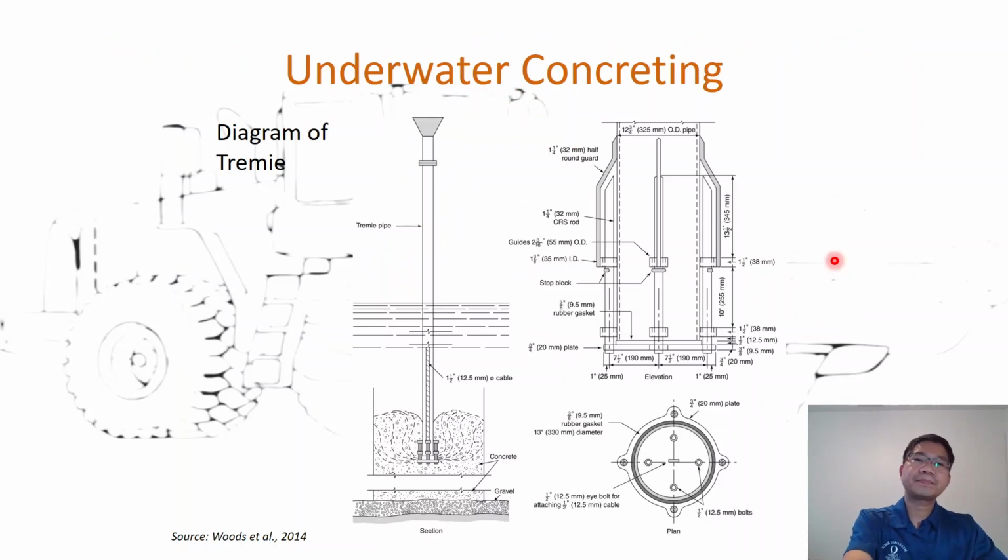And of course, concrete can be placed underwater. You study foundation construction, and I showed you different deep foundations. One of them, like a diaphragm wall or bored pile, always requires placing concrete underwater. And as you can see, this is the tremie used to put the concrete down, and it always maintains the opening of the tremie deep in the concrete so that the water will not get in, so you can place concrete properly with the water surrounding.